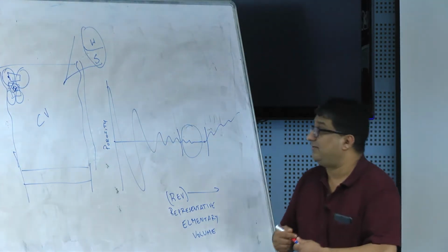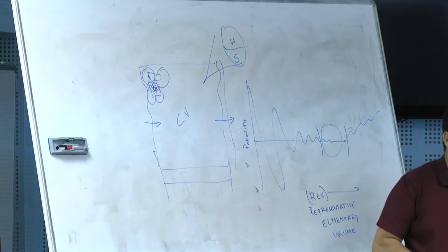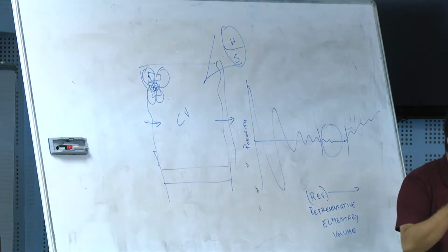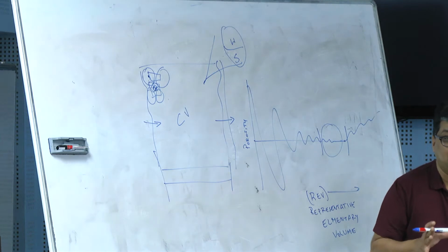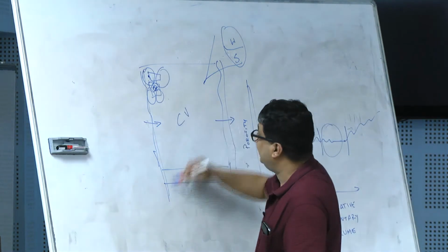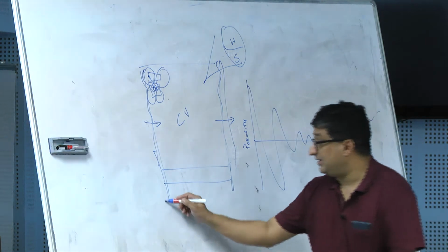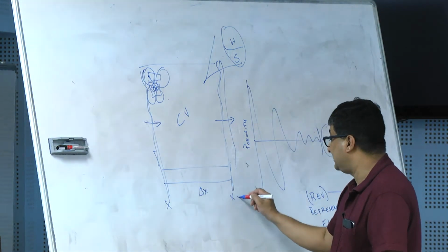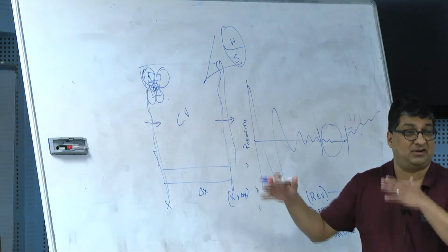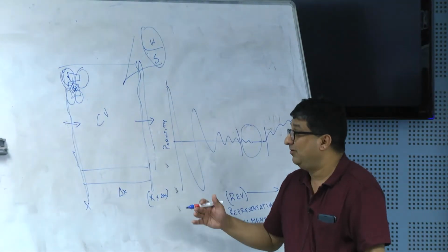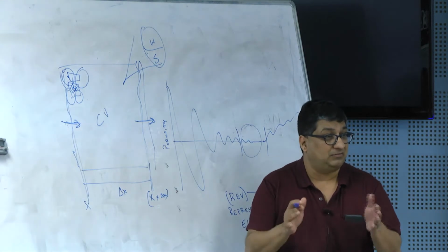Okay, so the transport phenomena, advection and dispersion, happen at the boundaries of our control volume. You can think of it as a numerical grid cell, or as an area or volume in the aquifer over which there is flow taking place, there is movement of flow. So right at the interface of that control volume, if I just take a section in the aquifer, right at that interface, I'll call this x. This is x plus delta x. But there is also y plus delta y, z plus delta z. So it's actually a three-dimensional cube. And what we say is the flux due to advection and dispersion happens at that interface of the control volume.